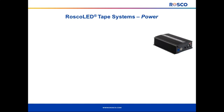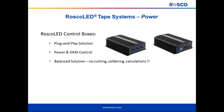We'll get into the power and dimming controls now on this slide. I mentioned earlier that we have a control box. This is really a nice, very simple plug-and-play solution. It incorporates a power supply and a DMX decoder inside the box. And as you can see from these 2 images, all of the connections are on the outside of the box. So you can plug in your power and your DMX in and out on one end. You've got your outputs for your tape on the other end using that multi-pin connector that's on our reels.